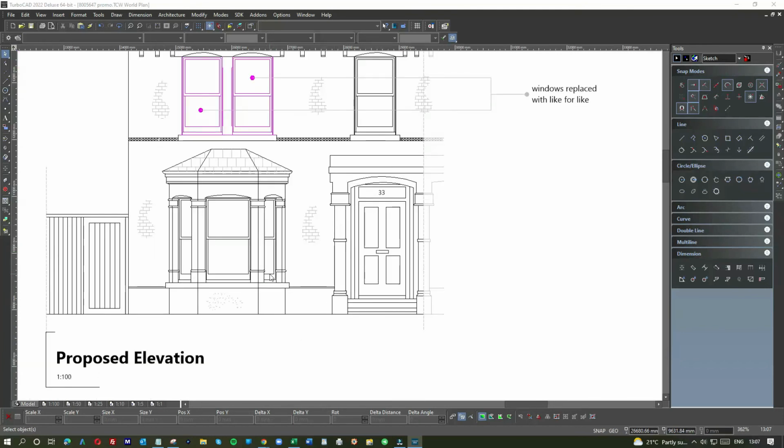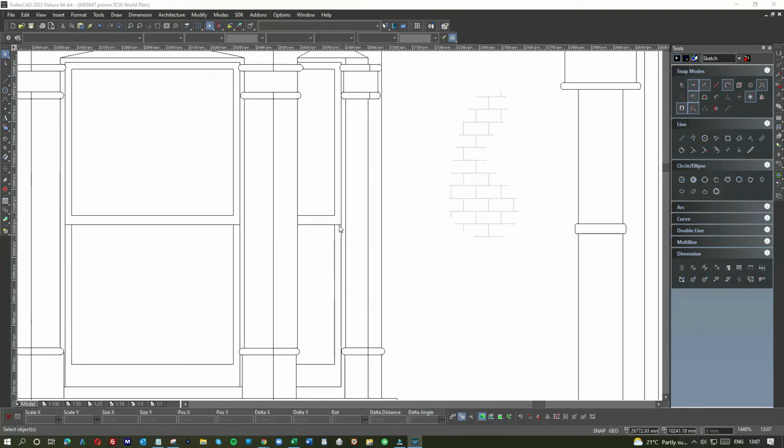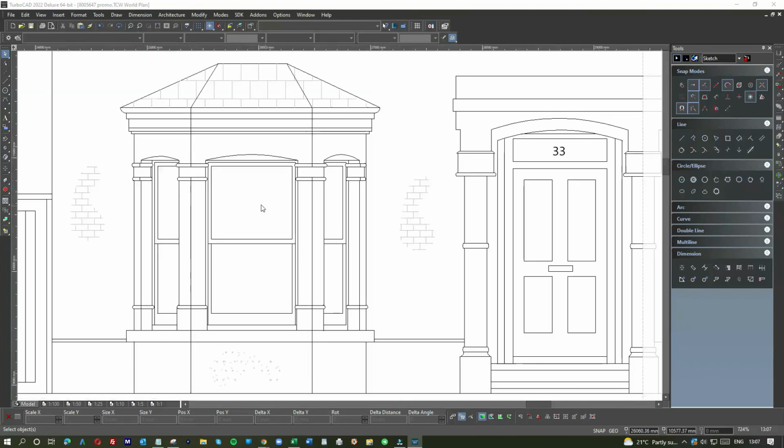And like I say, sash windows, get the heights, slightly different little profiles. You learn that because they're box sash windows, they're installed from the inside. It's not like double glazed windows installed into the brick. These are ornamental York stones, so all these windows are installed from the inside, and they're box sash windows.